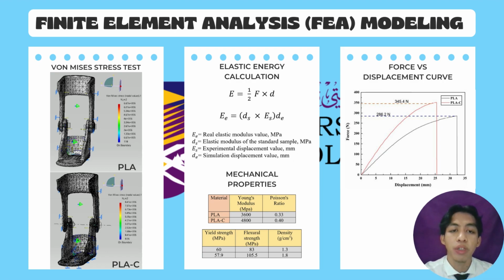The experiment demonstrated that adding carbon fiber to PLA increased its strength and robustness. When testing carbon fiber reinforced thermoplastics to make AFO, researchers noticed the same outcomes. Taking into account the fixation of the lower half and the loading at the other end, it helped to improve the correctness of the FEA model for this orthosis. The graph is the force displacement curve for both PLA and PLAC.